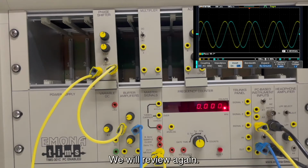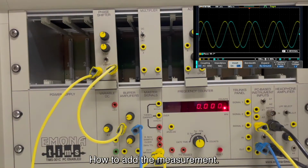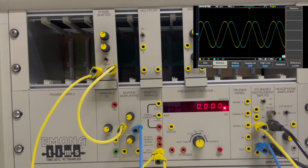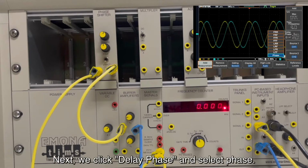We will review again how to add the measurement. Firstly, we press the measure button on the oscilloscope. Source 1 is channel 1 and source 2 is channel 2. Next, we click delay phase and select phase.